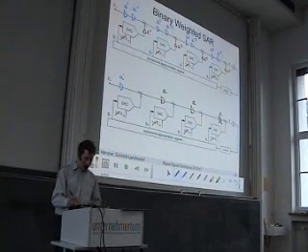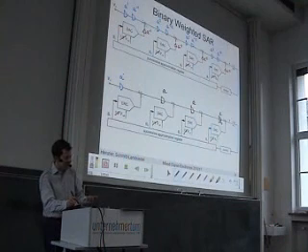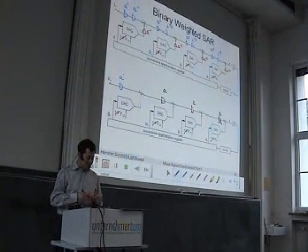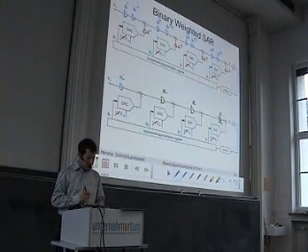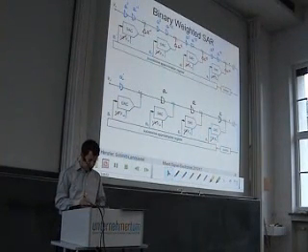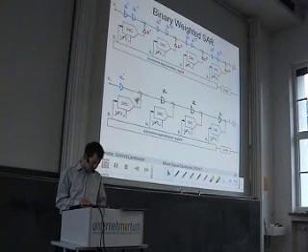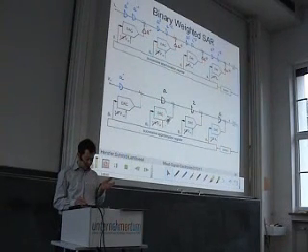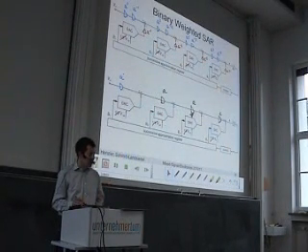So the interesting thing is now we have the same DACs with the same reference voltage, but after each step we scale the signal. So we do the subtraction here, and then we scale the signal up. We do the next step and we scale the signal up.